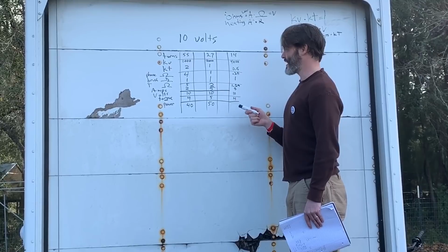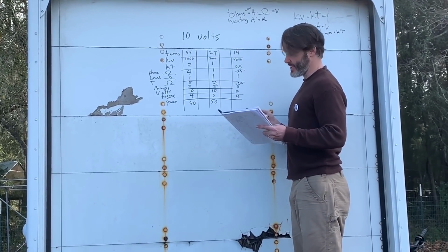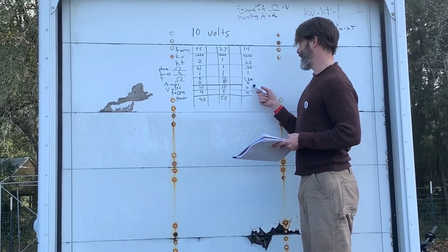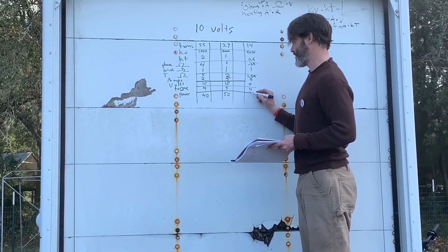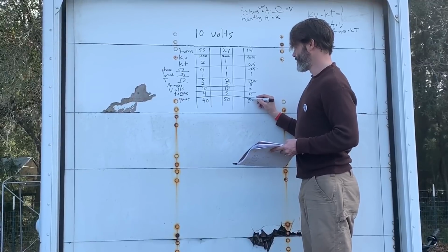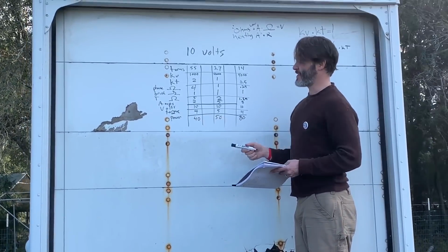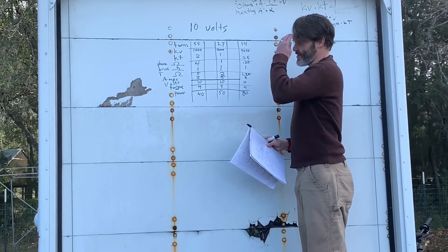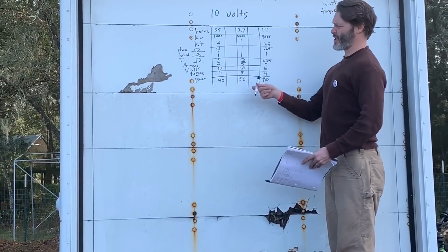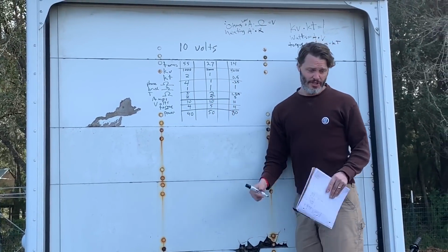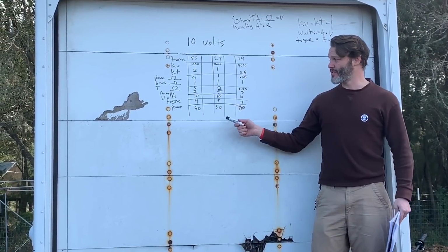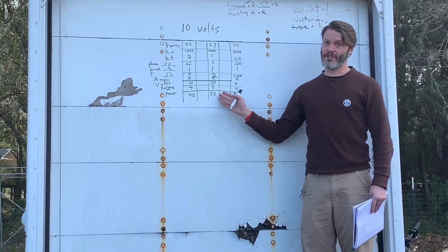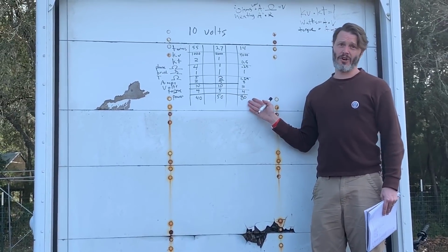But in this case, we are at, let's see, how many watts? We got 10 volts. We are at 8 amps. It took 80 watts for this motor to produce the same torque as the 55 turn did on 40. So as this lays out, you can kind of see there's a golden zone right here in the middle. This 27 turn motor is producing the most torque, and it's the same efficiency as the 55 turn, but definitely more efficient than our 14 turn at producing it.